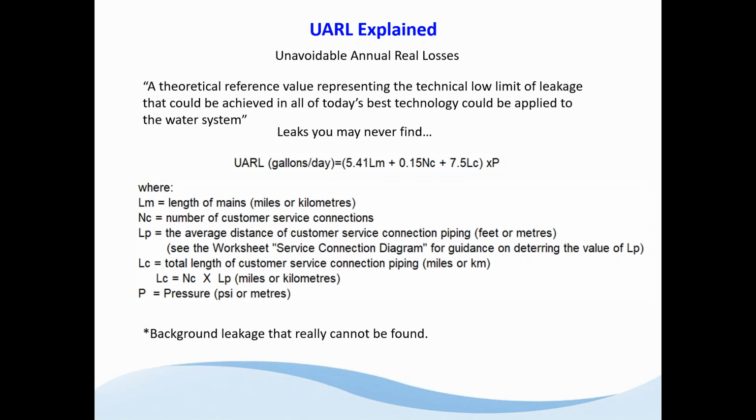Background leakage that cannot really be found. And in some cases, I think everybody here understands that in reality, there are some leaks that, because of their size, it is not cost effective to fix. A half gallon a minute leak on a joint on a 12-inch main in the middle of the busiest intersection in town probably is not going to be a huge priority, because financially it would be a disaster to dig that up to do that.